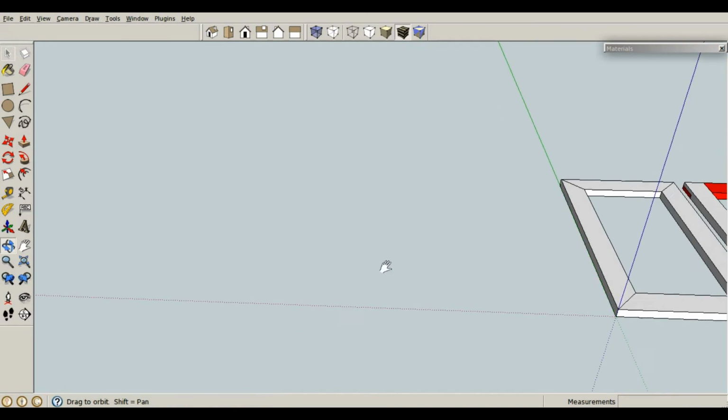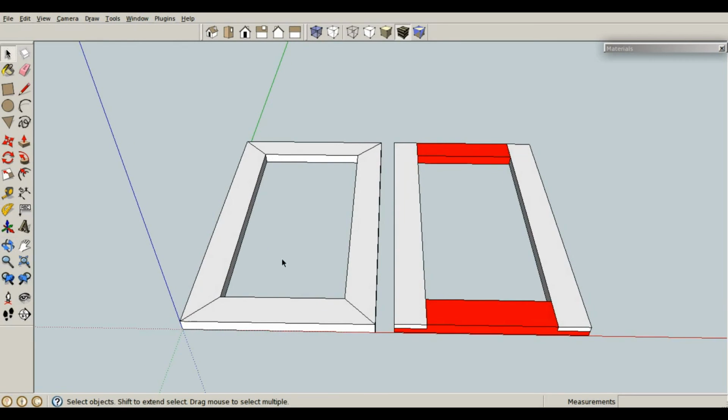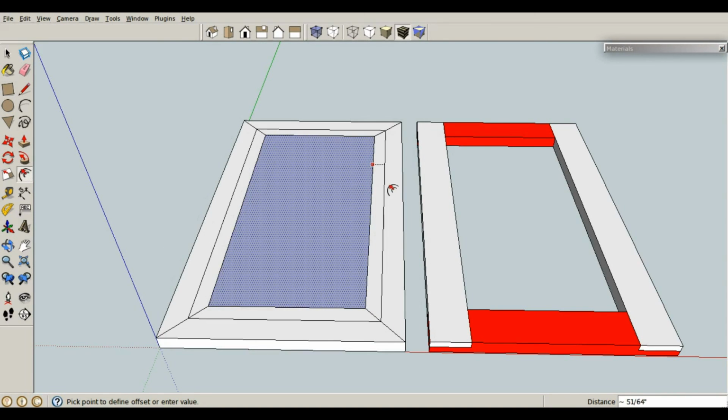But what about when we have somewhat complex joinery already together? So the simplest way to make a rabbet in a panel or something like this is to use the offset command to make guidelines. And what I mean by that is R for rectangle, and I'm just going to draw in space here. F for offset, select this line, and we want to be on the outside.